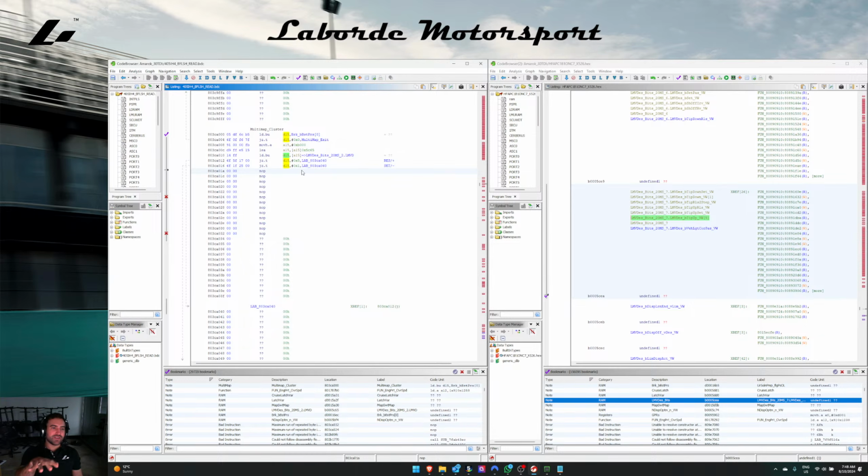We want it to continue to show what map we're at so long as the brake is held. That's called a latch variable. When we take our foot off the brake, the latch variable goes to 0. It jumps us out of that bit of code or function, and then the engine speed variable to the cluster is received from the engine speed variable that's derived from the crank and camshaft speed sensors and things like that.